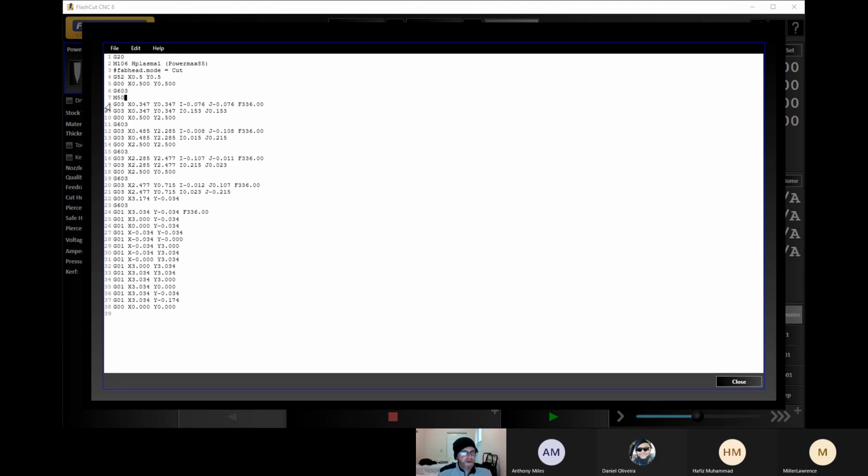Now, line number 8, that's going to be the lead that goes into the circle. We'll leave that as is. Line number 9, that's the circle itself. Between lines 9 and 10, there's a transition from G03 to G00.